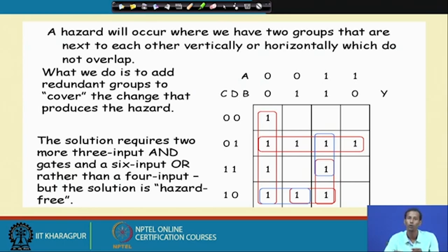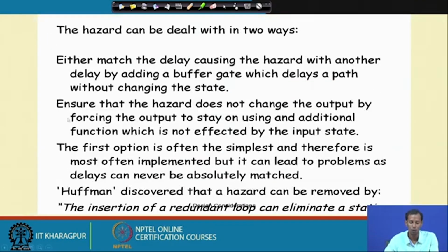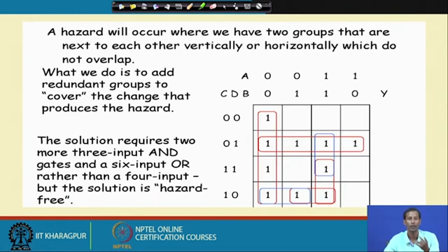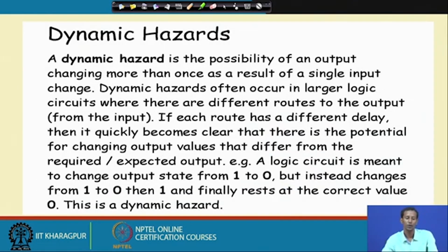So, that is why whenever you are getting a violation, that means you are getting some kind of glitch or hazard. At that time, by putting these two kinds of things, you can remove the hazards. One way is that you make the path balanced. Another is that you add some redundant logic to nullify the corresponding glitch which is occurring.